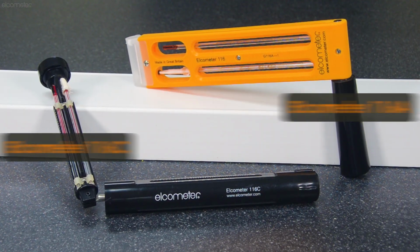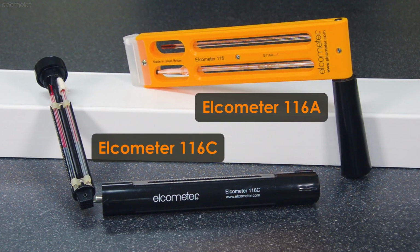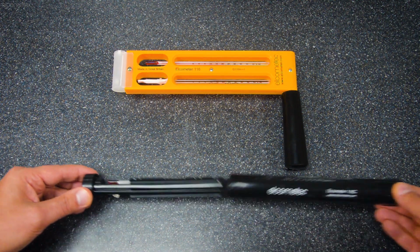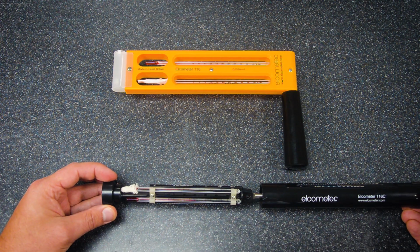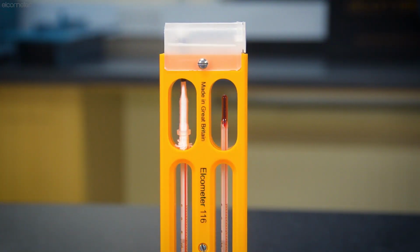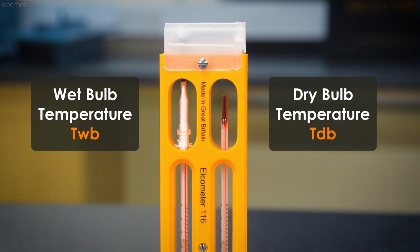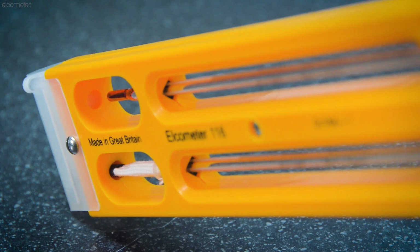Elcometer provides two types of hygrometer, but they work in pretty much the same way. Hygrometers consist of two liquid-filled thermometers positioned side by side in a rotating body. One thermometer is covered with a fabric sock or wick connected to a reservoir, this measures your wet bulb temperature, while the other is uncovered, this measures your dry bulb temperature. While the dry bulb thermometer is measuring what is thought of as ambient air temperature, the wet bulb thermometer is used to calculate relative humidity.